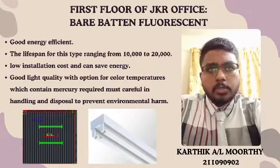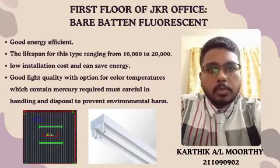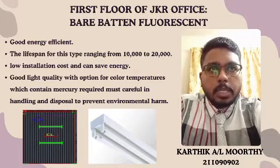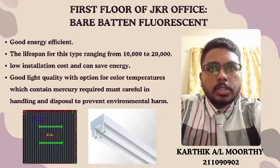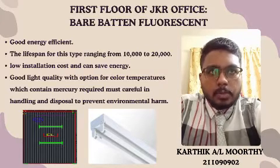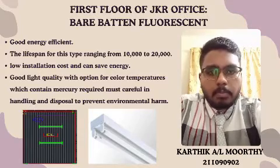TLD is standard 2 times 36 watt because this type is good for energy efficiency. We also choose 2 times 36 instead of 1 times 36 because the brightness can cover a wide area. The lifespan for this type ranges from 10,000 to 20,000. Then we choose bare batten as the type of fitting because the area has a shielding, so this type of fitting is easy to install, low installation cost and can save energy. These luminaire types have good light quality with options for color temperature. They contain mercury, so they must be handled carefully and disposed of properly to prevent environmental harm.